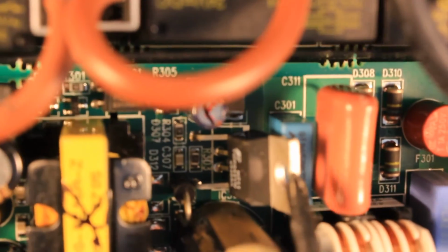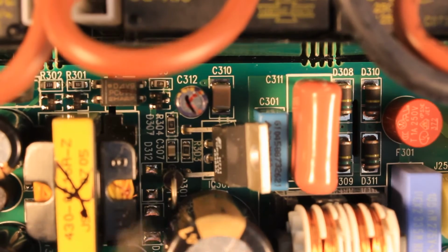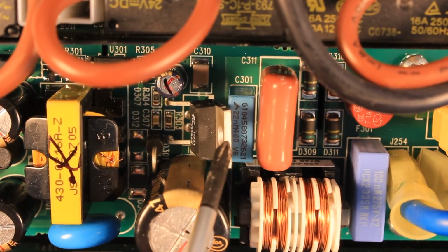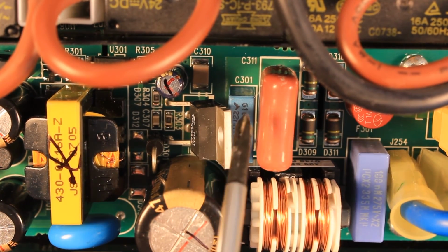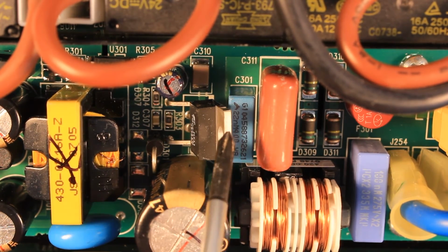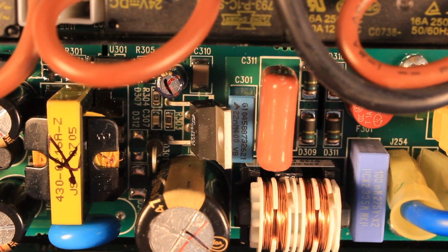Then, as I mentioned, they are using a TOP244YN monolithic integrated circuit, which is already ready-made exactly for these switch mode power supply applications. In fact, according to the datasheet, up to 34 watts, if I remember correctly, you don't even need to put any heatsink on the circuit, so it's pretty well-designed stuff as well.